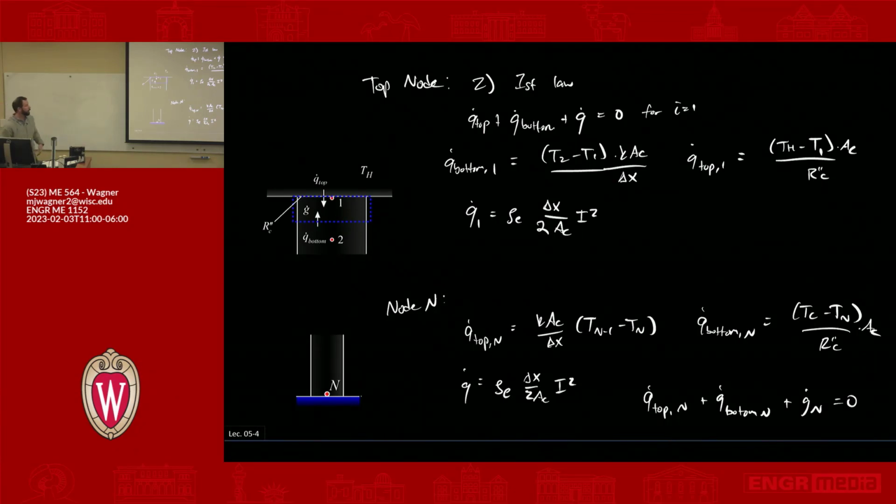OK, good. So now we have n equations, n unknowns in our temperature. We should be able to take this and plug it into EES and solve it, or anywhere and solve it, right? The way we formulated this, all the T's are kind of embedded in the equation, so you'd have this implicit solution. But you can do that in EES.